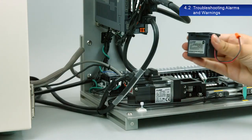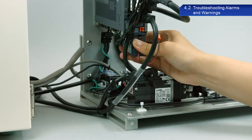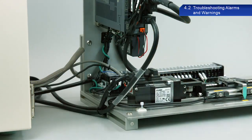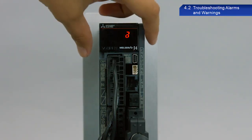I will now describe the procedure to reset absolute position information if lost. First, replace the battery. Then, perform the return to origin position process. Turn on the power to the servo amplifier and make sure the alarm has been cleared.